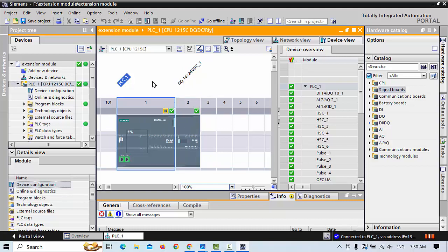Also, when you are working in the field, there may be many modules connected with your PLC and some have a problem or error, but you can't see anything. Go directly to the software, upload, and go online. After that you can see in your hardware where the problem is and solve it. Maybe it is a power supply issue, maybe an internal jumper fault or any fault, you can solve it easily.